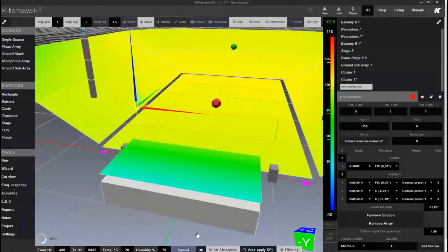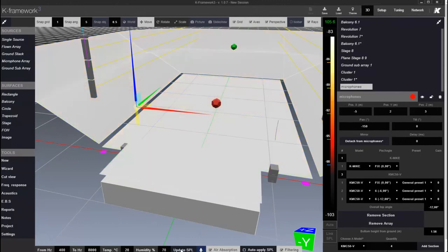Clicking on this button, we basically flip to the other side. So we can see where the microphones are shooting and how much. Basically, it's an attenuation scale. So we swap here and update. The colors are changing. It's no more a dB SPL, but a dB in attenuation. One second, we will see the result. Here on the right, you have the new scale with the new colors.